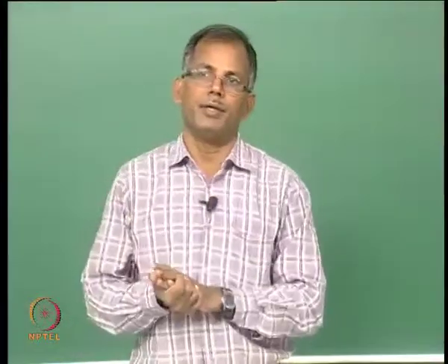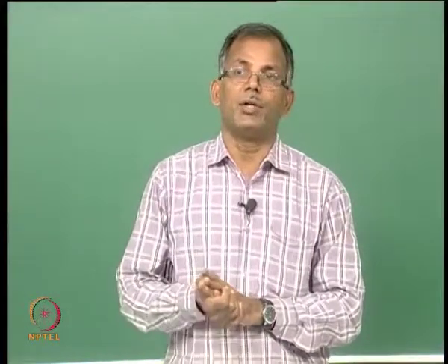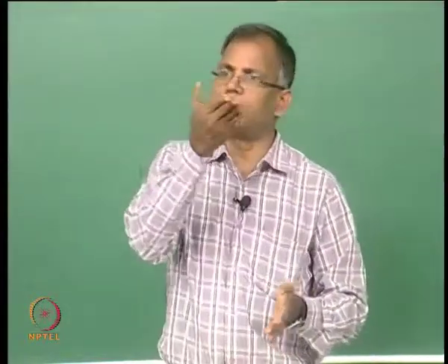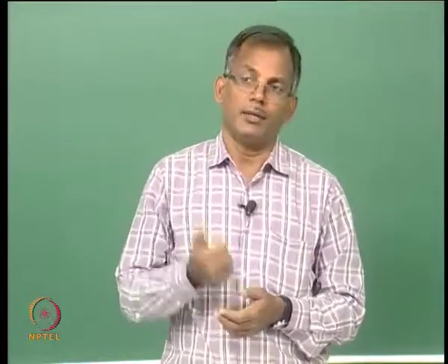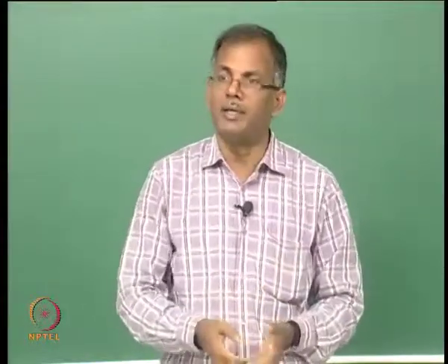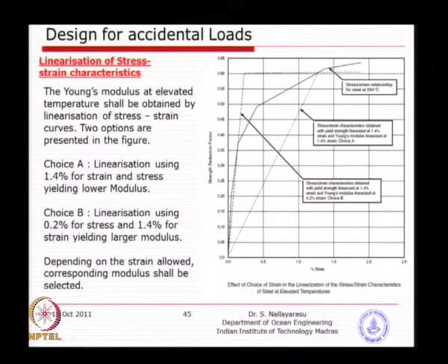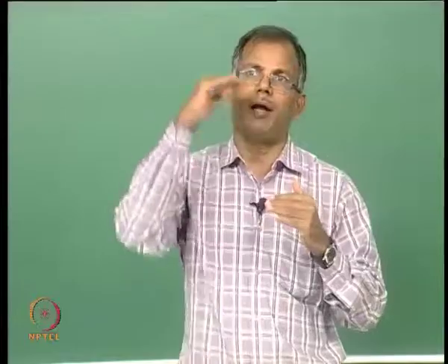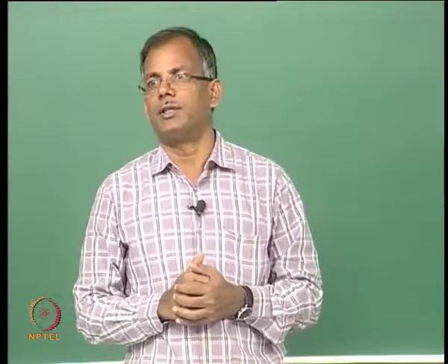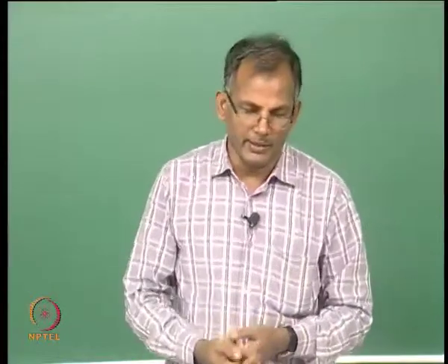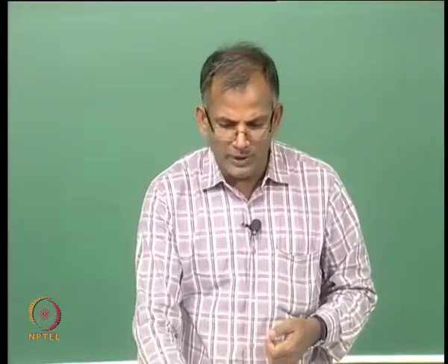0.2% and higher. Whenever you have a material characteristic that is not bilinear, I will show you one of the bilinear graphs. I think we have seen it before also, a straight line and then perfectly plastic, and for that type of problem you do not need to worry, whereas here you see multiple segments of linear proposition, continuously changing from the start itself, which is a typical behavior for steel under increased temperature. I think that is what we saw yesterday, several graphs in one picture for steel at 20 degrees, 400 degrees, 500 degrees, and you will see that there is no longer a bilinear graph.